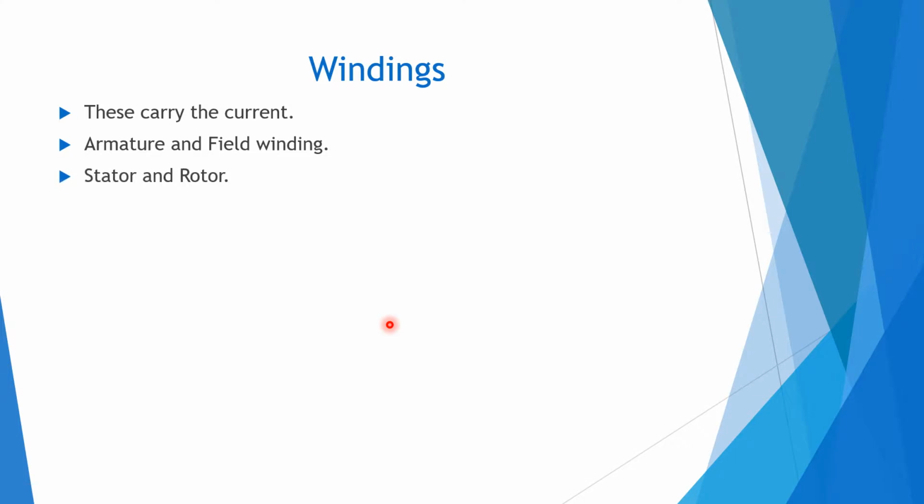Then you can also segregate them on a stator or rotor basis. In any rotating machine, there are basically two components: one is the stationary component, and one is the shaft, which is the rotating component. There should be net movement between these two, and something which causes net torque production between them. In an electrical machine, this is because of the magnetic field interacting with the coils. It is not necessary that the field has to be produced by the stator and the rotor has to experience the force. Sometimes the other way can happen, where the rotor produces a very high magnetic field and applies a force on the stator, and by Newton's third law it will apply an equal and opposite force.